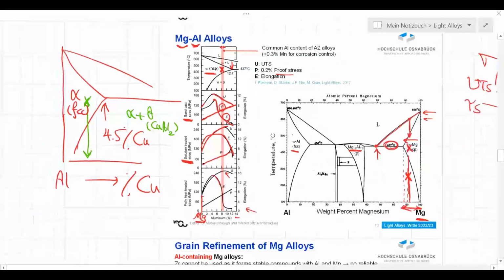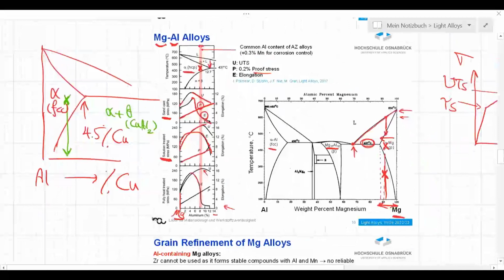Now, in this case, it is not possible to get those intermediate phases. We directly get the stable beta phase, right? And beta has this chemical composition, and that is unfortunately not going to give us the strengthening. So it doesn't help much to think about precipitation hardening of this alloy system, although from phase diagram, one might get the impression that it's going to be an attractive concept.